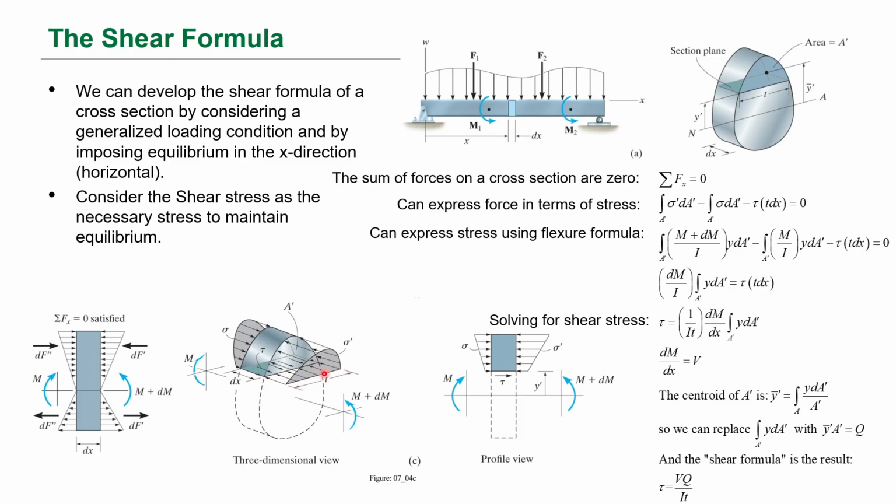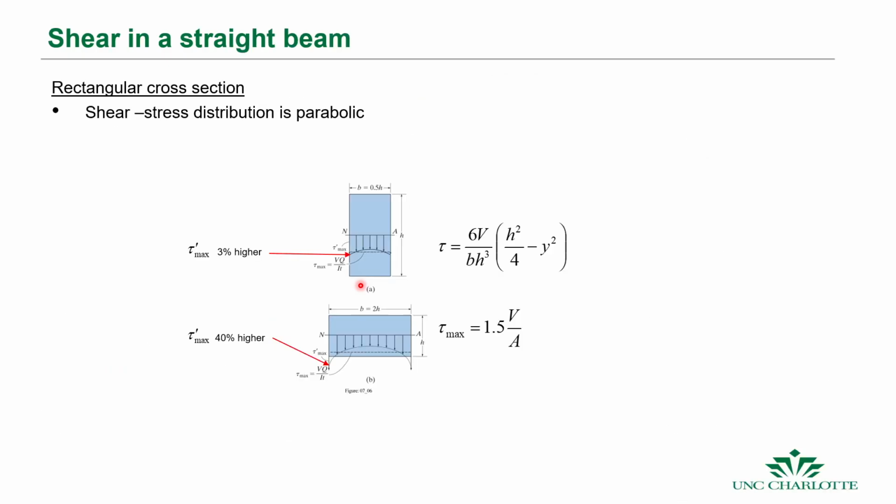Okay, these details are important for you to understand where we're actually calculating the shear stress. So we can actually calculate the shear stresses using the shear formula at different locations along the thickness, but we just have to make sure our area, centroidal area, shear, thicknesses and moment of inertia are used properly.